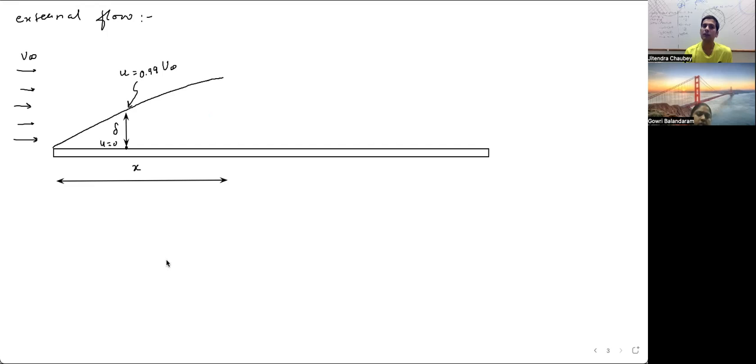When the thickness of the fluid keeps on growing, there comes a point, because of its own weight, where the uppermost layer tries to descend. It tries to get inside the lower layer. That is where disturbance is caused, where the turbulence propagates, where turbulence of the fluid starts. And that zone is called the transition zone. So that is laminar plus turbulent.